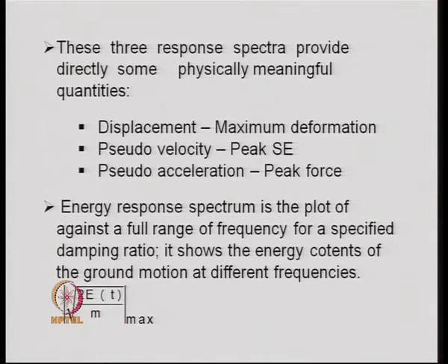These three response spectra provide directly some physically meaningful quantities, namely the displacement response spectrum provides the information about the maximum deformation that takes place in the single degree of freedom system. Pseudo velocity spectrum provides the peak value of strain energy in the system, and pseudo acceleration spectrum provides the peak force in the system.